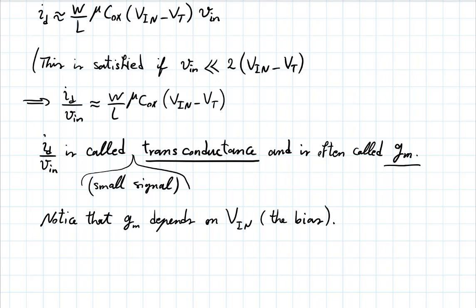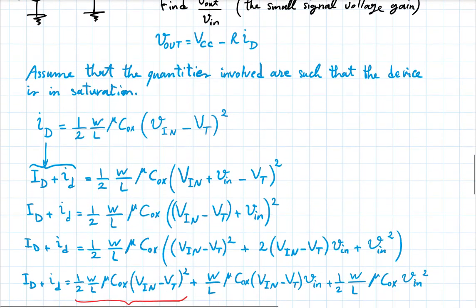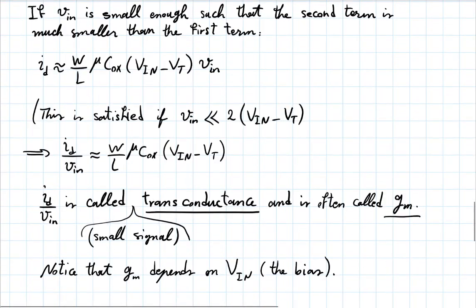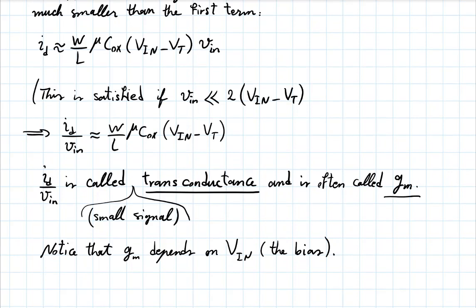Of course, there are other worries, right? Because if I have, in this circuit, if I work around a very large input bias, then my output will be pretty low, right? I risk leaving the desired mode of operation. If Vout is too low, I can very easily get into the triode mode. So there are trade-offs. But you can see that as a first step kind of thing, if you want a higher gain, give it a slightly higher Vn.